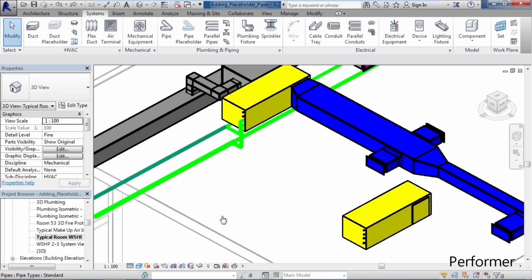So they don't have some other things as well. They don't have the ability to align vertical or horizontal, and they don't have the ability to add linings or insulation. But these placeholder pipes can be converted into a regular pipe. So when you use a placeholder pipe, you still pick the type of pipe and the material and the settings, but again, it's mostly used for conceptual design.